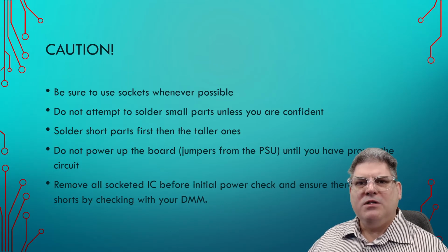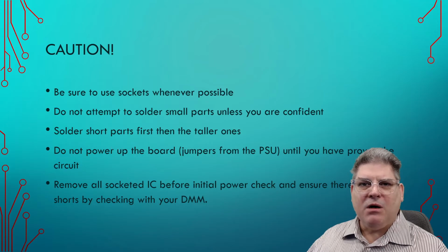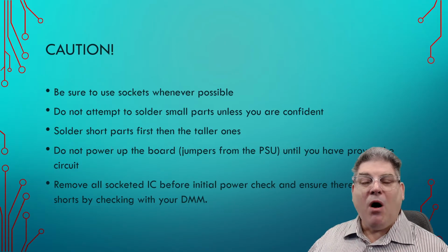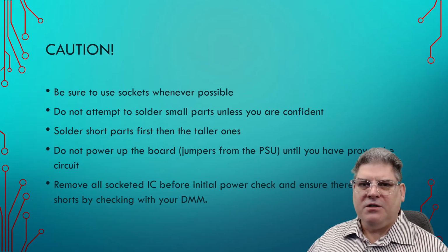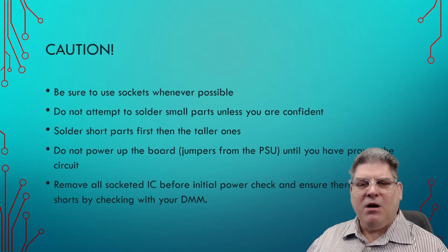Okay, so for me, I solder all my SMT parts first, and pretty much do the really big stuff like a heat sink at the end, if possible. If you're putting it in the reflow oven, that's another situation altogether. But know that you need to be able to get in at the small parts to be able to place them and then work your way up.